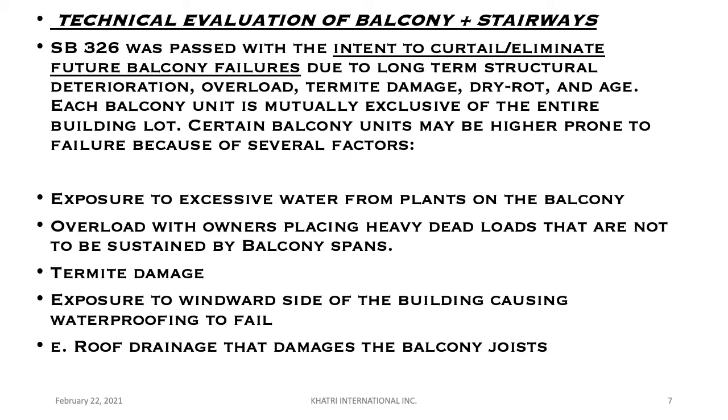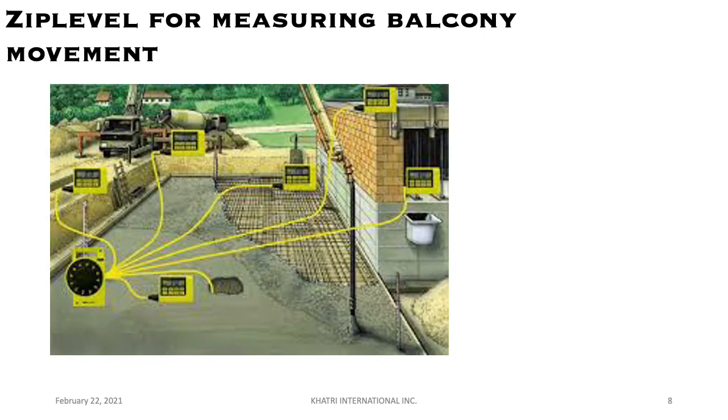So you have to think of the project as each balcony is a separate structure, independent of the other structures. They are all tied together to the same building, but you cannot really make a sample size conclusion from that. So when we come, or whoever you hire, but at least in our office, when we come to do the evaluation, we will use this instrument, which is called a zip level. It's essentially a level survey, and this is just an illustration.